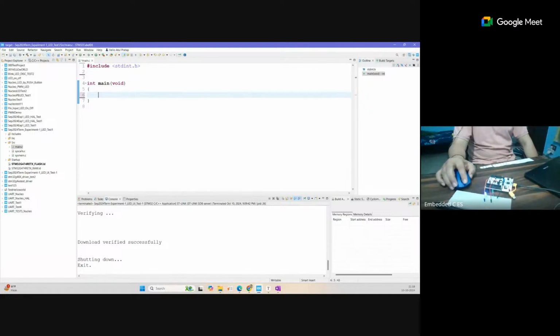Because of that we will use this standard stdint library for the microcontroller. Here we will only use the number of bits which is actually required, not more than that, because our concern here is memory, as we have limited memory on the microcontroller. Our target is the same, and all our connections are there in the same way. We know the port numbers PA5 and PB5.